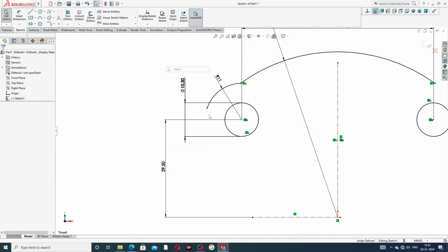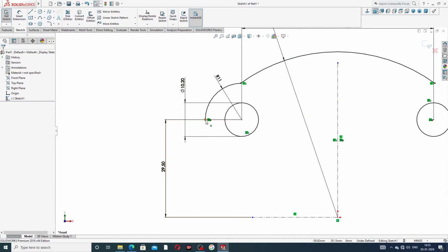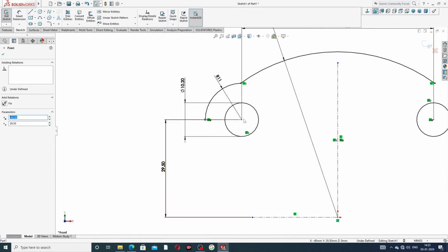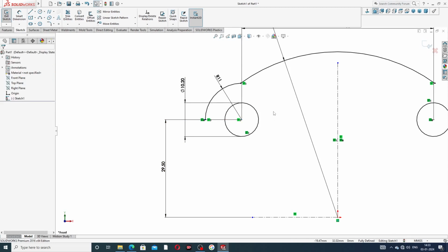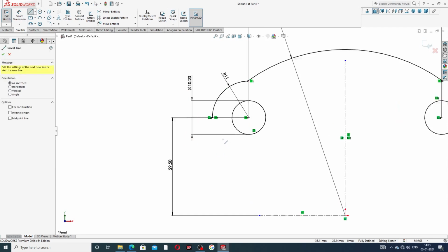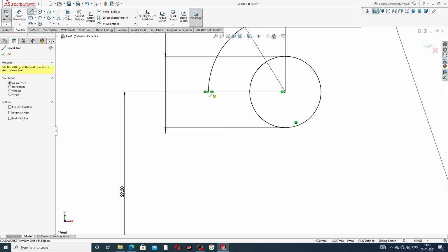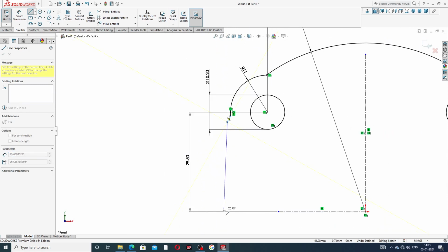And some important points, this line is a drag here, and these two points have a horizontal relation. Okay, and this is a very, very important relation. Select a line, draw some line, drag it horizontal, and some inclined, and connect to this.